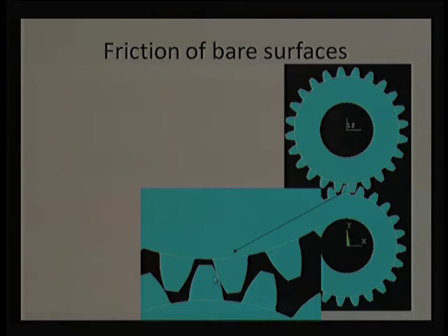If surfaces are without any lubricant and they need to rotate, naturally there will be high friction. Coefficient of friction may even reach 0.6, 0.7. If surface finishes are not very good, and surfaces are not hard, they deflect easily, then that will not be desirable, because gears are used for power transmission, not for power losing effect. We want to transmit the power as much as possible.